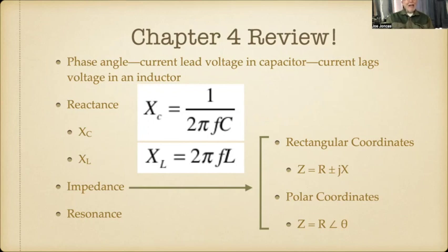inductor, the current lags. That's because as soon as you apply a voltage to the coil, it radiates out a magnetic field, which causes back EMF. So the coil, which is first getting its current, radiates a magnetic field out, which then in turn stops the current from flowing. And then slowly the voltage or the current increases. So it's the opposite of what a capacitor does.